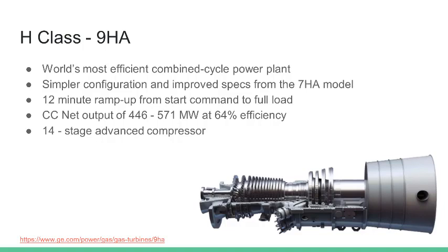It is very cost effective due to its fuel to electricity ratio, and the new specs it has over the 7HA are a 4-stage turbine with 3D aerodynamic hot gas path, cooling and sealing improvements, single crystal and directionally solidified blades, as well as a double wall casing for improved clearance control.